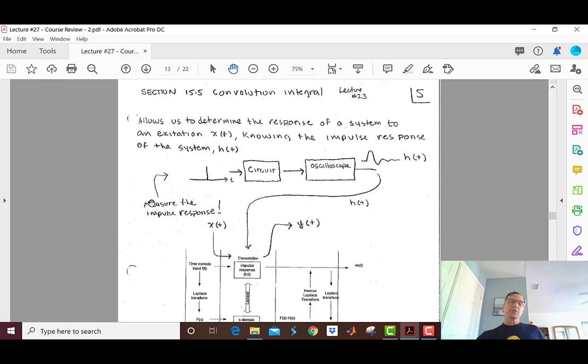So to measure the impulse response, we give it a whack in the time domain. I'm an engineer. A clap is a whack, and it goes through the circuit, and then I'm just going to measure the output with the oscilloscope. So, hey, here's one. Let's take a crack of lightning. It makes an impulse when that spark goes by. You get an impulse. But then it bounces off all the mountains and it goes through all the inversion layers in the air. And by the time you hear it, the thunder doesn't go pop like when you shoot a light bulb with a BB gun.